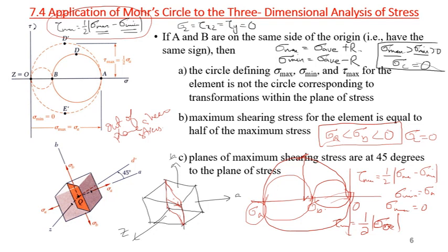Now, let's suppose you have to design something. It's a ductile material, and you have a plane stress state. But if you take the in plane shear stress, then in that case the system will fail, because you have calculated with respect to in plane, but the maximum is out of plane. So you have to be careful during the calculation of those stresses.